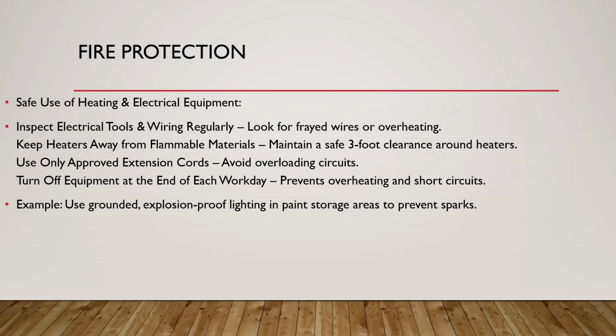The safe use of heating and electrical equipment. Inspect electrical tools and wiring regularly. Look for frayed wires or overheating. Keep heaters away from flammable materials. Maintain a safe 3-foot clearance around heaters. Use only approved extension cords. Avoid overloading